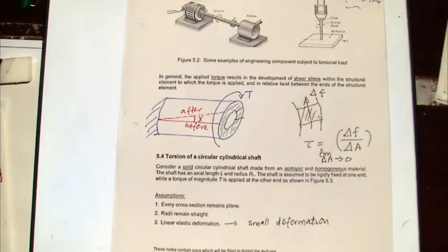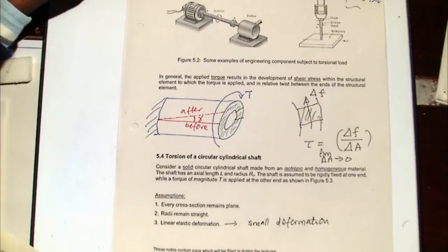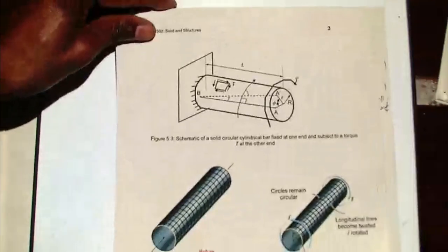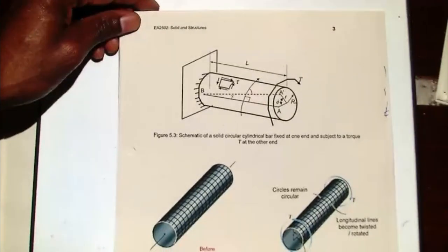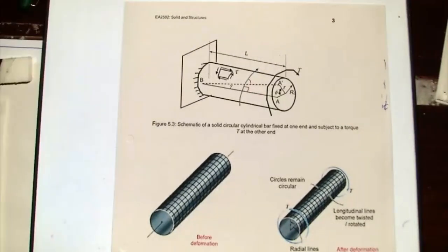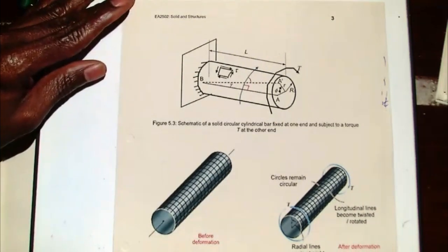So we have a circular cross-section like a shaft. We apply a twisting torque in Newton meters. We want to find out what shear stress is developed in that particular cross-section. So let's quickly look at what that will look like. I'm drawing this, and you'll see it drawn many times. It's similar to what I've just drawn. I've got an initial line along the axis, and I've got a torque applied. That line has moved to a different location, and we want to look at the relationship between the movement of that line and the magnitude of the torque on it.